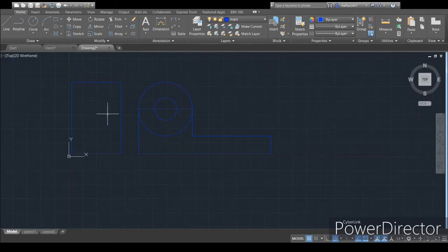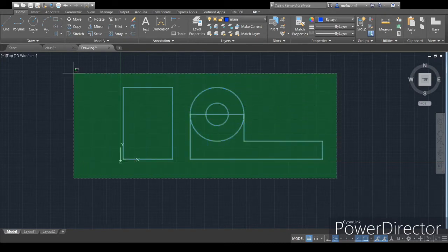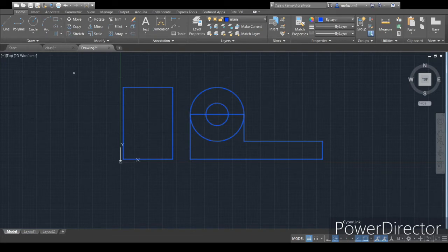Now what you want to do, shrink it down. We have to go ahead and do a couple of trims. So if you go from right to left, click it once, drag it, it'll select everything, click it, everything's selected, press enter, erase that, erase the center. Okay, now when you're done, just press escape, click on the extra line you don't need, and click delete.